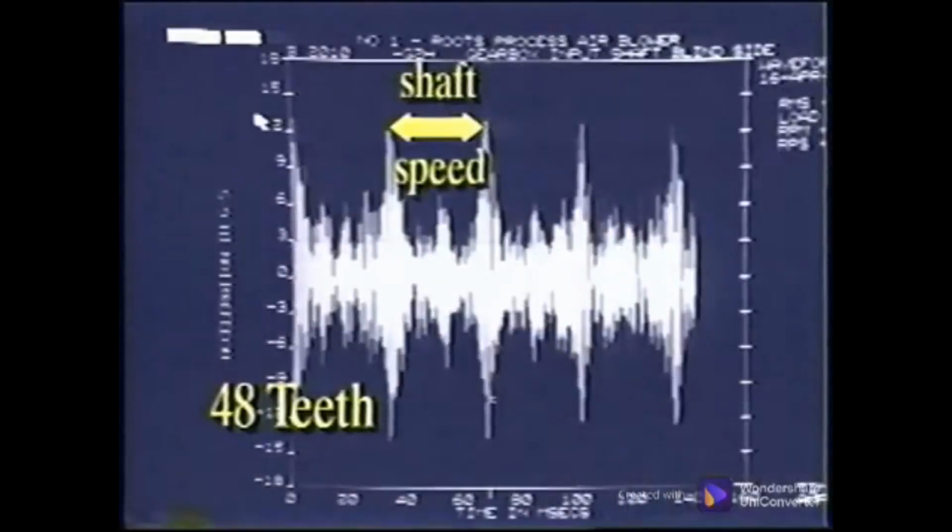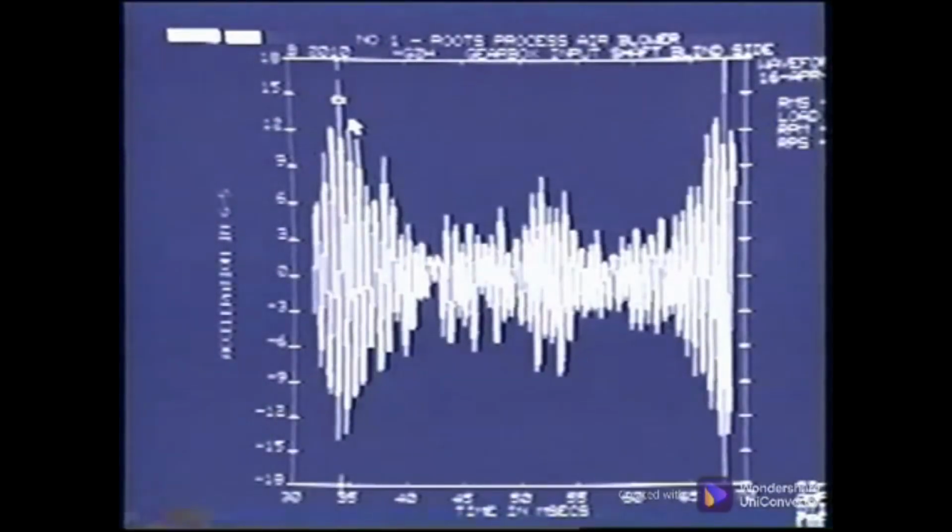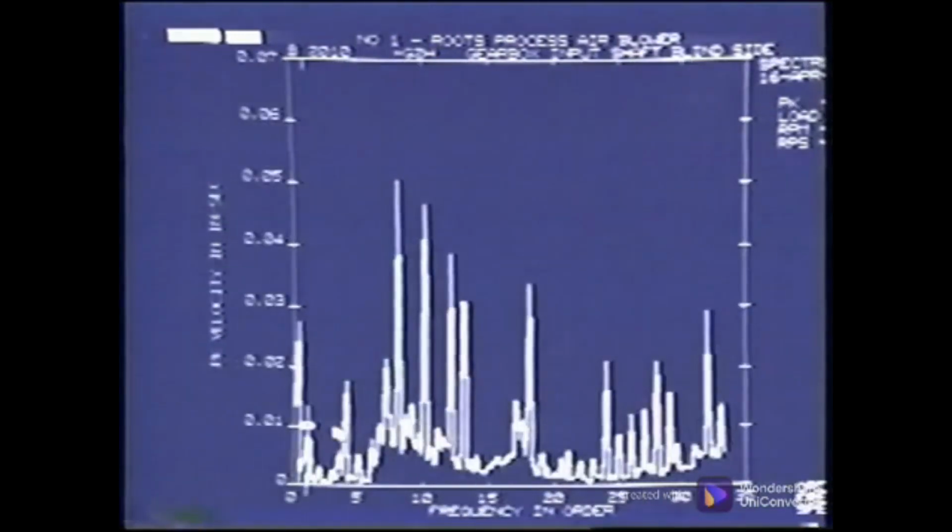The gears on this shaft have 48 teeth. The high impacts are spaced at the shaft turning speed. As expected, the expanded waveform shows 48 impacts during each shaft revolution. The waveform data clearly shows the significant 1 times turning speed event. This is a result of amplitude modulation, which is more dominant in this example.